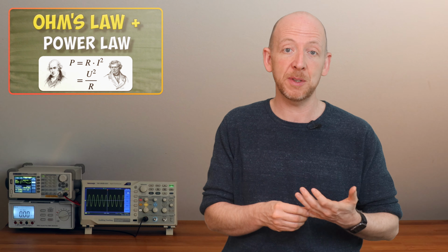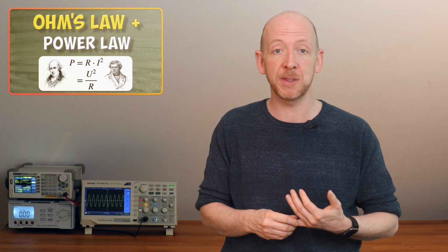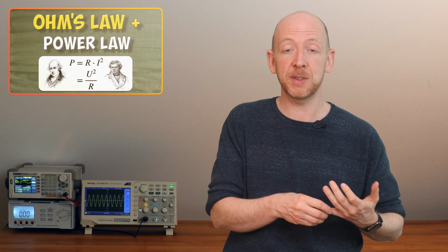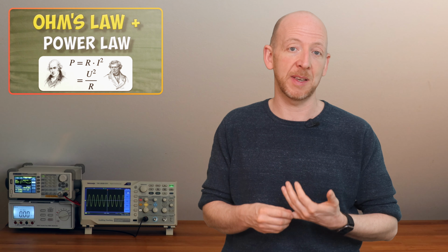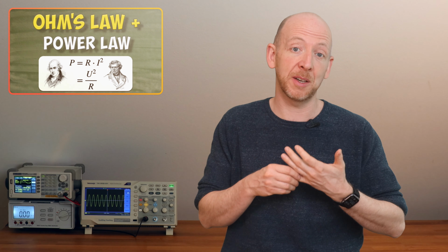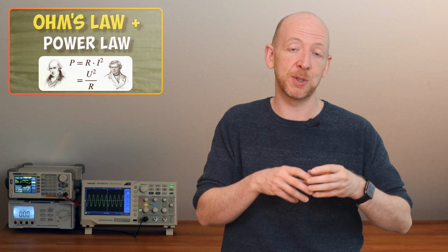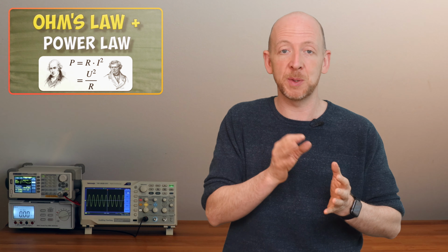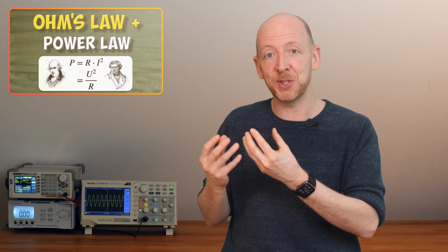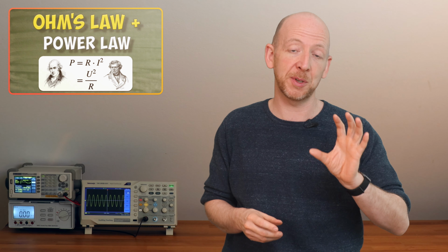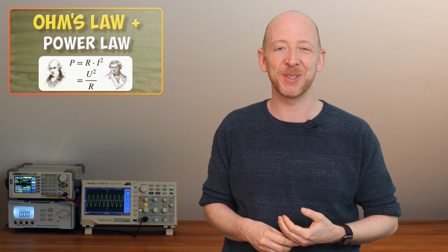And thirdly, we have seen two variants of the power law. The voltage variant of the power law should be used when a constant voltage source is being used in a circuit, let's say a battery. And lastly, the current variant of the power law should be used if a constant current source is present. And a constant current source is a source which does not, or does only to a very small extent, change the current it supplies to a circuit if this circuit changes its resistance. So for current sources, current stays constant. For voltage sources, voltage stays constant.